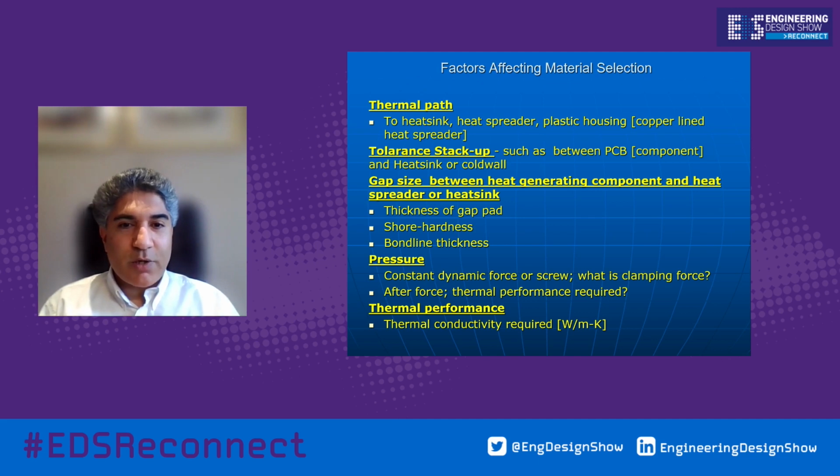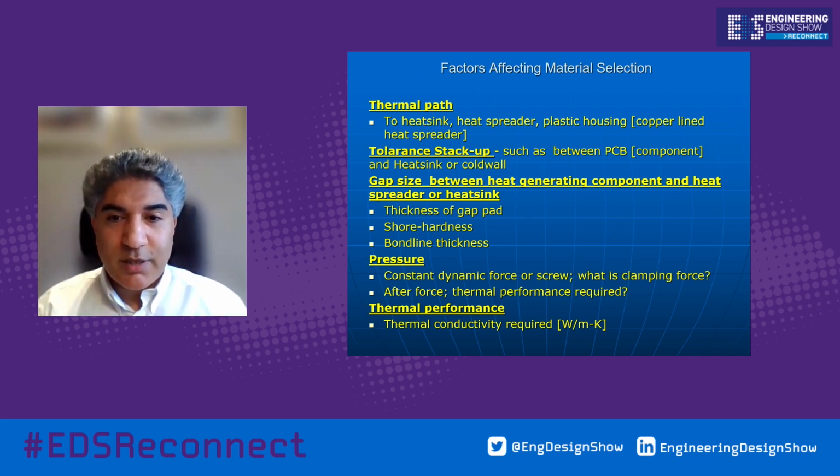Some applications require thin bond lines. They understand that the thinner the material, the more it lets the interface do its work. We just want to fill in the nooks and crannies. Contact pressure is needed to make sure it's evenly distributed, so obviously controlling the deflection. If you're using a gap pad, you want to avoid over-deflecting and having compression set, so you want to be able to reuse it and avoid it reaching compression set, where it doesn't recover its elastomeric properties.